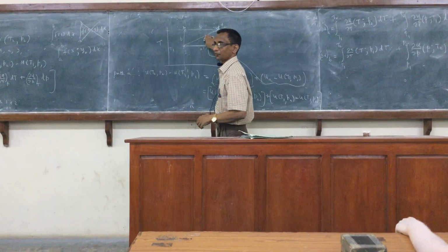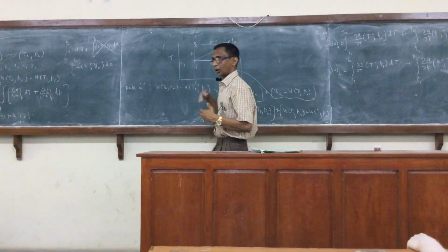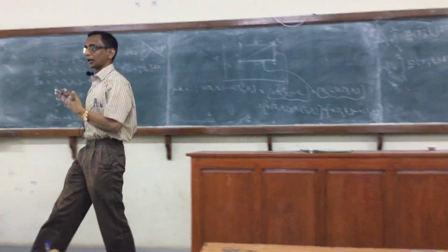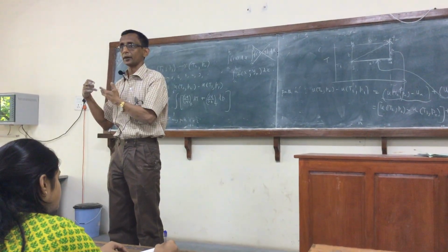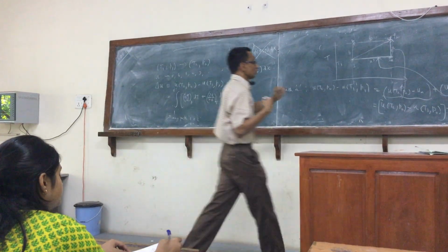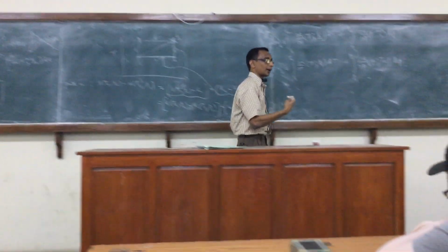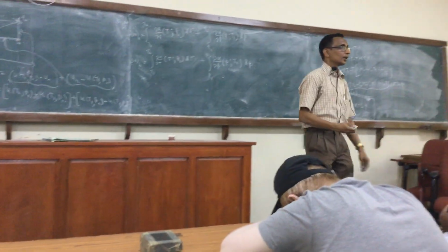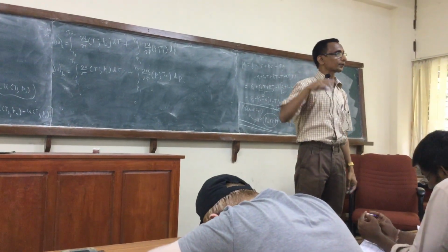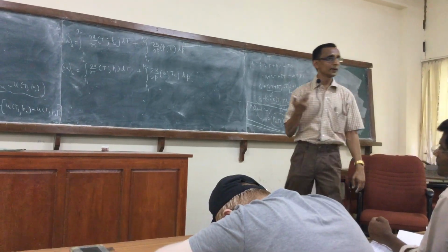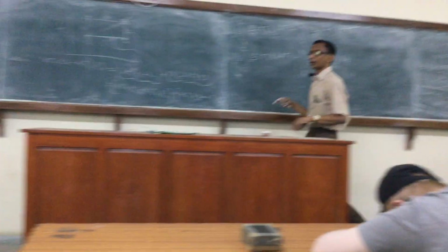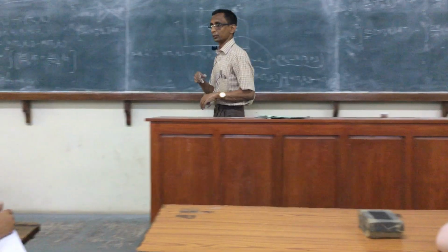That would again make it difficult to calculate because along the path, both temperature and pressure are varying. So rather than choose a single path, I am splitting it into two paths. One of which is a constant temperature path and another is a constant pressure path. So I can split it into two integrals, integrating with respect to only one variable at a time. That is the advantage.